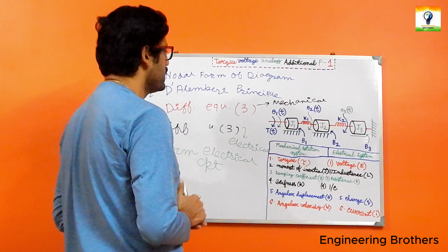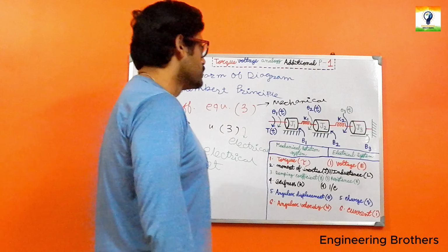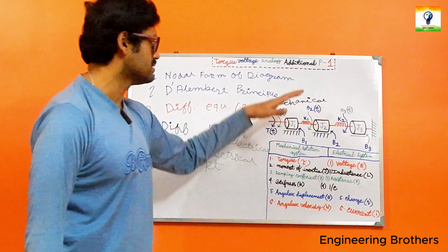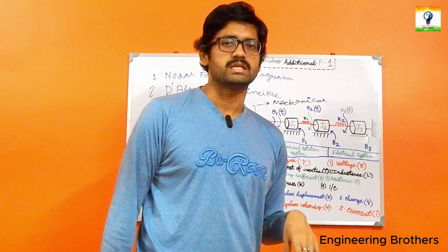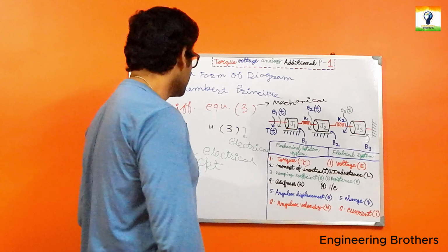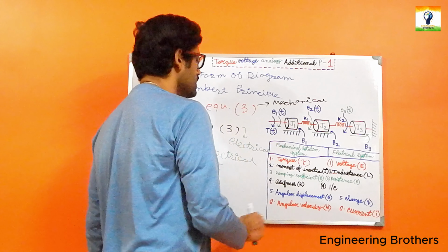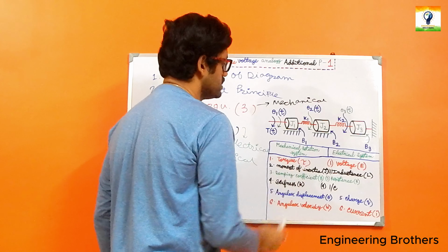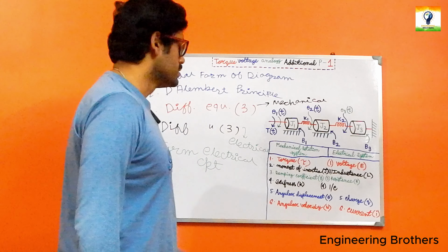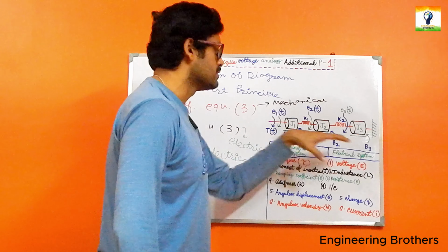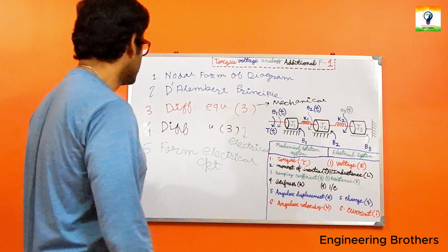After I have applied that, we have got three differential equations, and I need to mention that this differential equation is naturally the mechanical one. In the next stage we need to convert that mechanical equation into the electrical one by using this chart or analogous table. That will be our fourth stage.